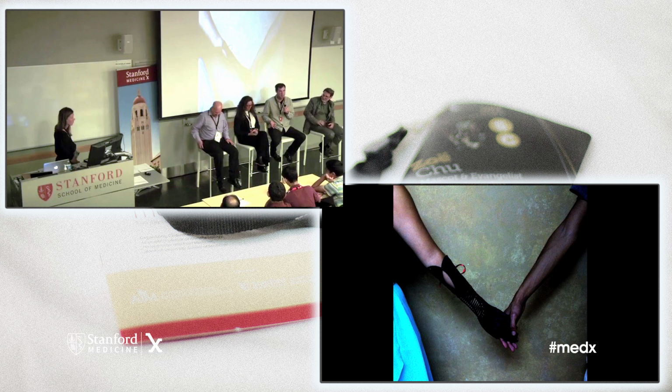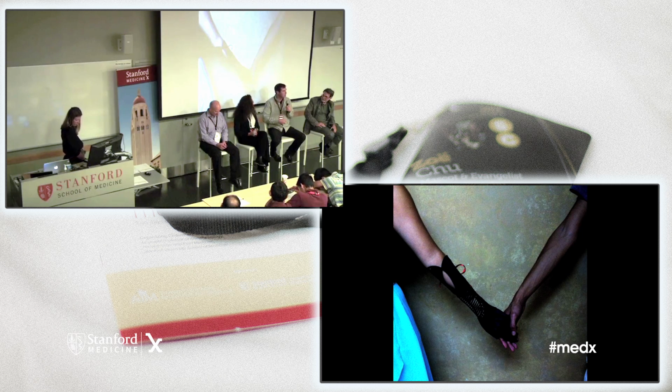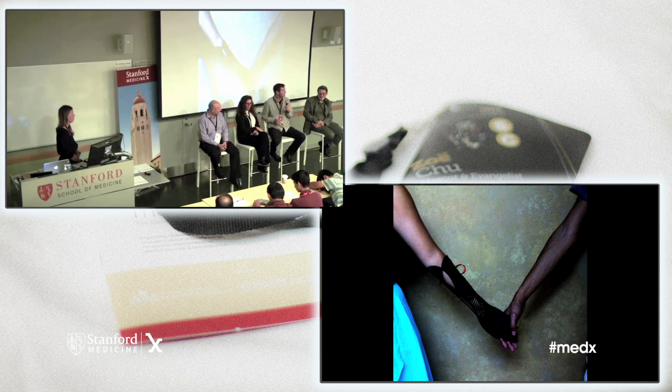Same thing went on with hearing aids. Acetabular hip cups, if you need a hip replacement, knee replacement, all kinds of different bone replacements, they print it in a trabecular lattice structure that promotes bone ingrowth, so it actually promotes very effective osseointegration. They're printing out of titanium, 17-4 stainless, all the biocompatible metals. Gaining a lot of traction now are PEEK and PEKK, which are also biocompatible polymers. And so we're seeing a lot of those for implants now. So even though we aren't printing our kidneys and livers yet, there are plenty of solutions all up and down the body that actually are being 3D printed for very significant purposes.